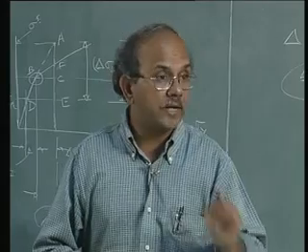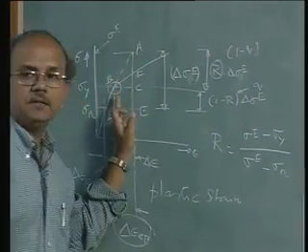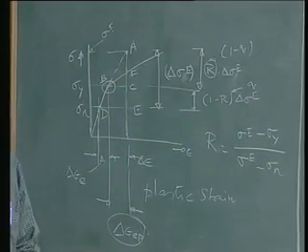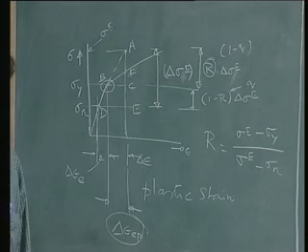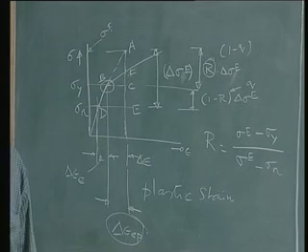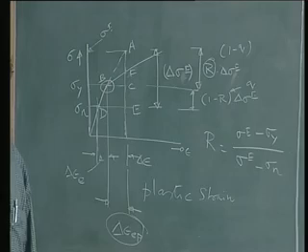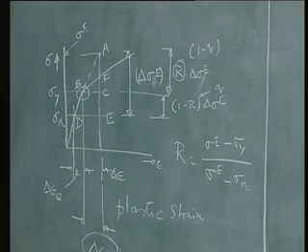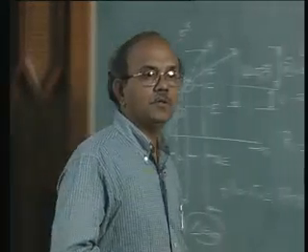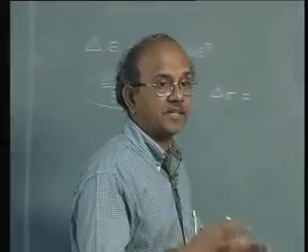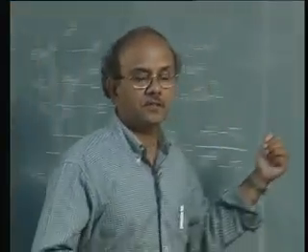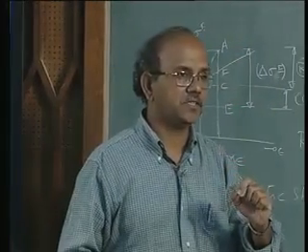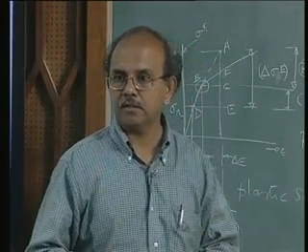So in spite of the fact that when I reach the yield point, my slip starts growing, or in other words the dislocation starts moving, my lattice distortions do not cease. They do not cease. They also take place along with my slip. So when both phenomena are active in this elastoplastic region, I have both elastic strains and plastic strains. Does that answer your question?